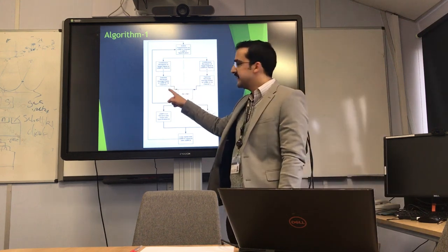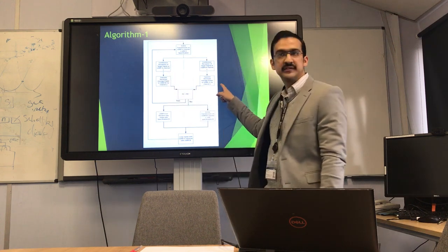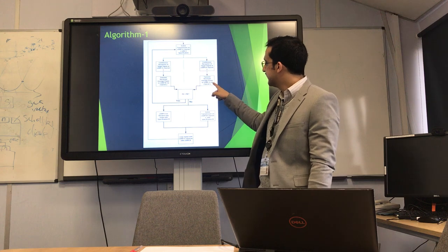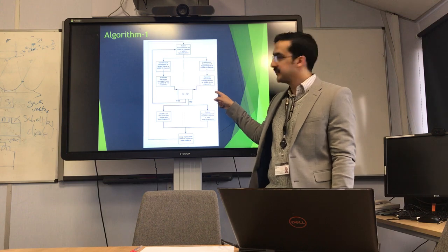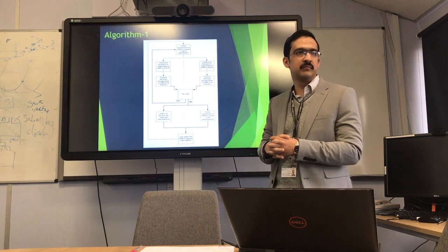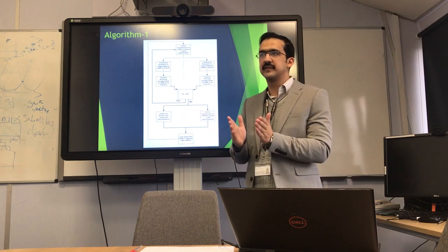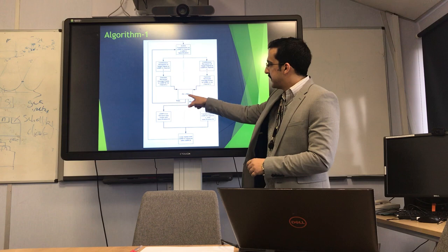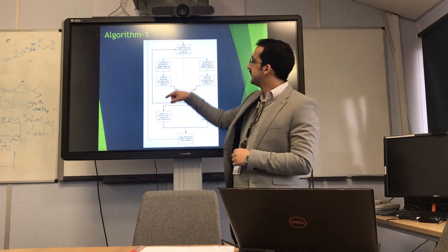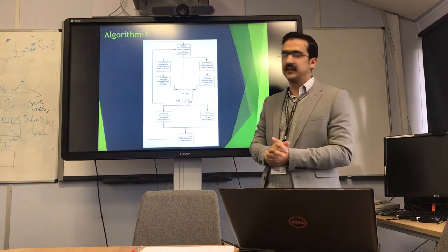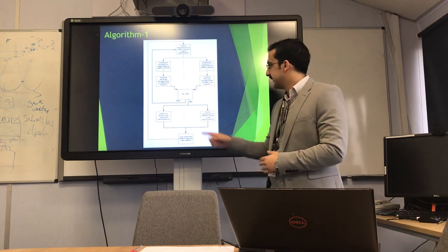And we transmit the received average power that is being received by USRP A to USRP B, and the received average power of USRP B to USRP A with its different channel. So it's kind of a radar-comm hybrid solution, taking into consideration the 2 different channels. The power is being compared. If the power of A is greater than the power of B, the same loop keeps on repeating, nothing very difficult.